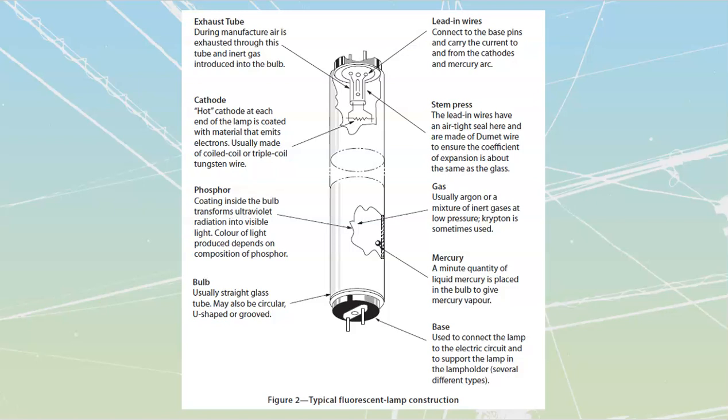So at the very top of your page above this, they talk about bulb shapes, and they talk about T12, T8, T5, T17, etc. And they don't really explain what those things are. But what they are is the number that we are going to see, or the size, is going to be 1/8 of an inch.